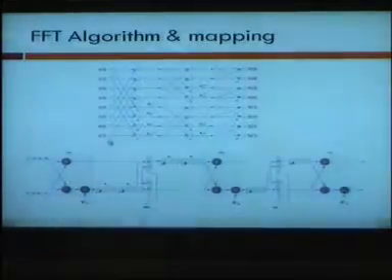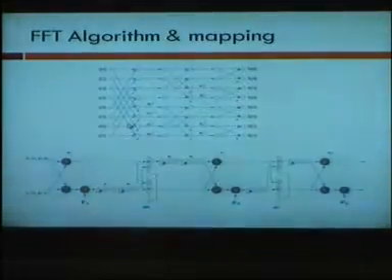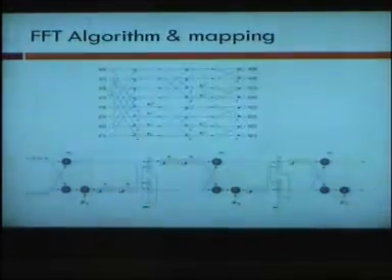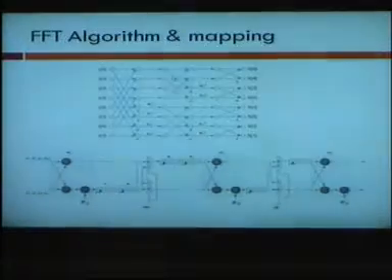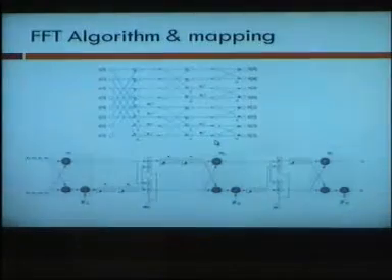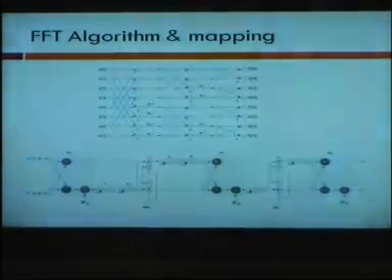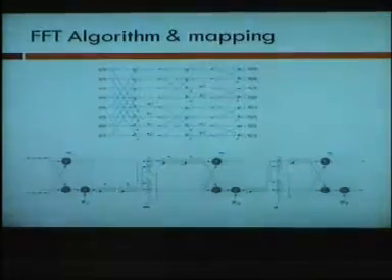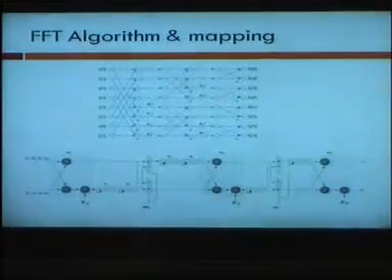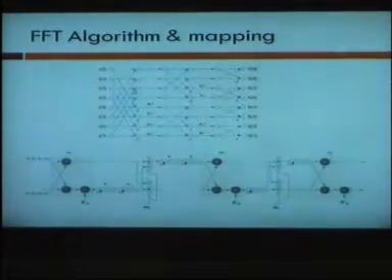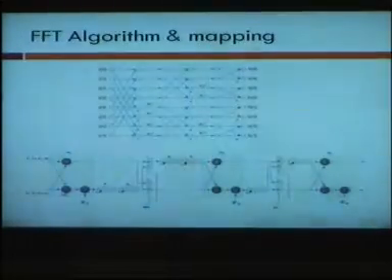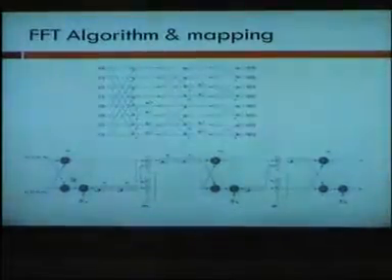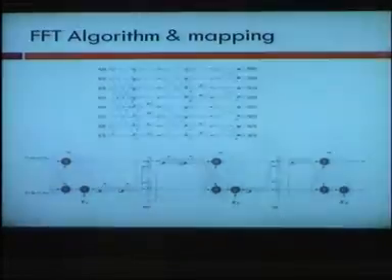And this is a hardware implementation. It's a very interesting, not very easy to conceive design, where if you count, these are 1, 2, 3, 4 butterflies. And in every stage you have 4 butterflies. So it's an algorithm which requires 12 butterflies if you're doing it in software. And now in the hardware mapping, what it does is that instead of implementing 4 butterflies, in hardware it only designs one butterfly. So at every stage there is one butterfly. What you see is the hardware. One butterfly, and one butterfly.